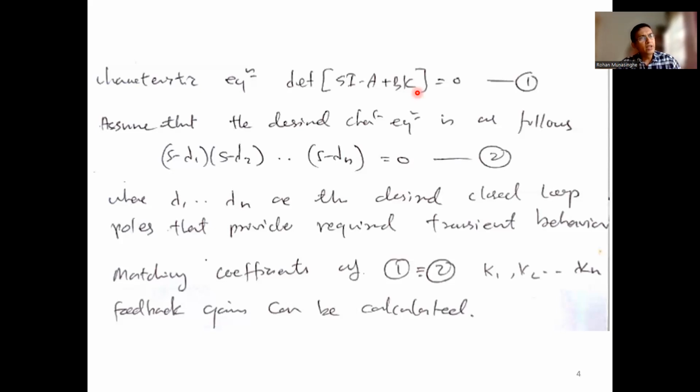Through the gains and through the feedback, what we are trying to do is probe into the closed loop poles to see where they are, and move and locate them in an appropriate manner. This is a variable characteristic equation, so you can mold it into various shapes.